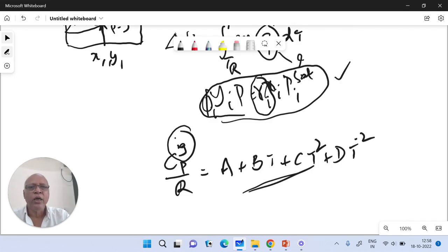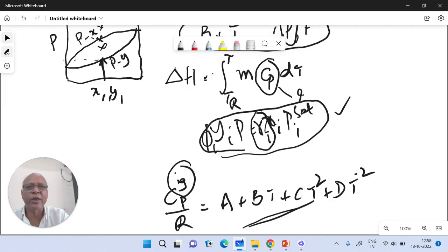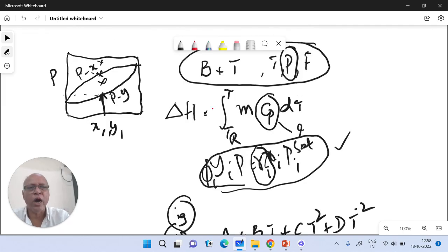And for example, if you try to make use of this, remember these data are available for pure components, but we are dealing with a mixture of benzene and toluene. How are we going to evaluate the property of the mixture? Are we going to take some kind of mole fraction average? Again, there are some mixing rules which will also come into picture, especially when the pressures are high, to have an accurate result. Having done this, if you are using something like ideal gas state, how are we going to calculate the actual enthalpy in the real gas state?